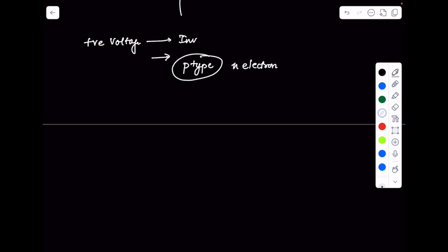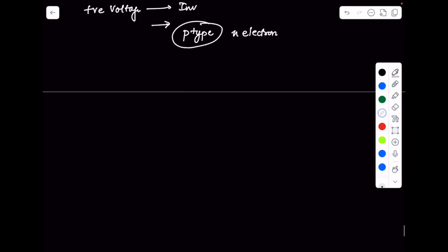Are they high frequency or low frequency? They are high frequency characteristics because we see that the Cmin is reduced. In inversion, the capacitance doesn't come up to Cox. Now, the second question asked is, what is the gate area of the MOS capacitor?